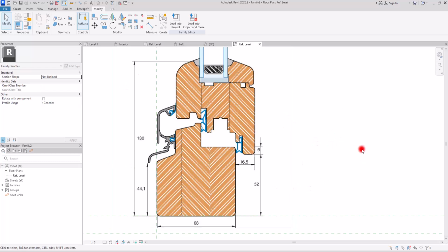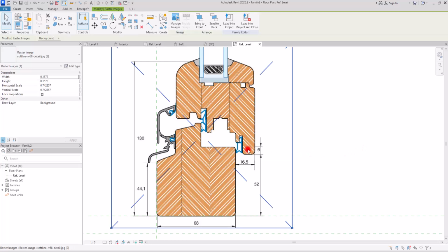So to prevent that, we are going to first select the image and pin it in itself so we can't drag it or move it away. And then to prevent these highlight, we don't want to see it like this. We want to just have a background. We want to have this image as background, as reference. And for that, I'm going to just uncheck this part.